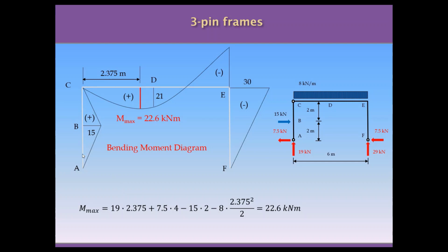So now the distribution of moment is different in this column. Big moments appear in the second column, and the bending moment diagram is not all positive anymore, so we have areas with negative moment, and actually the maximum moment is 30 now and located in this corner instead of being located in this position as in the previous example.